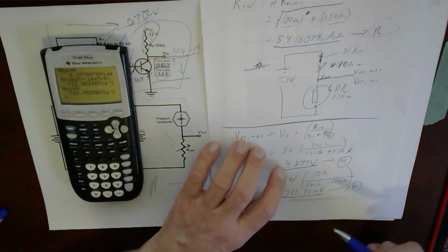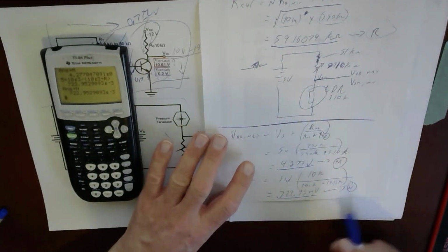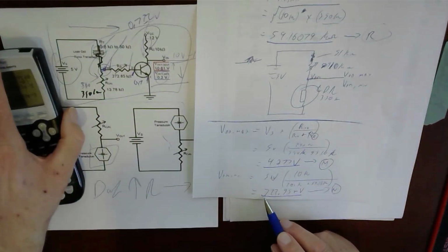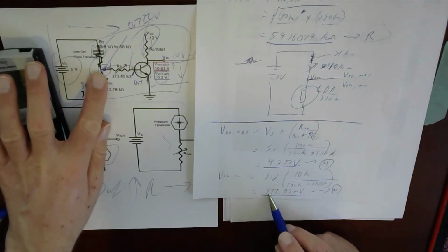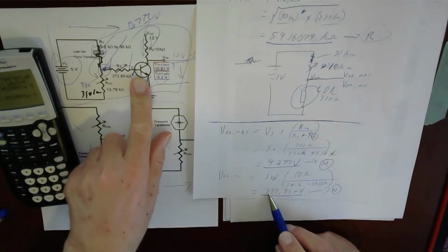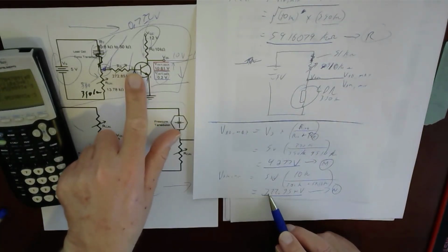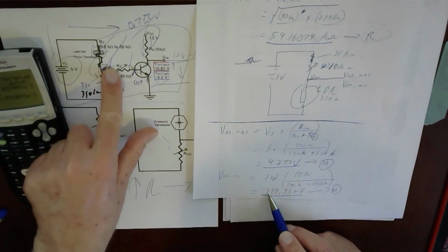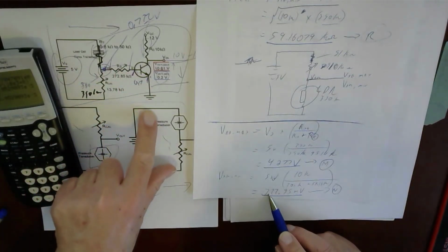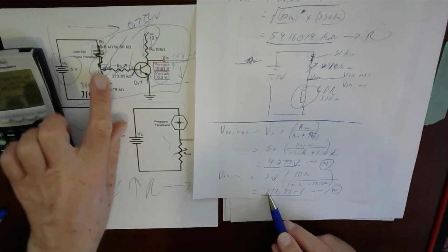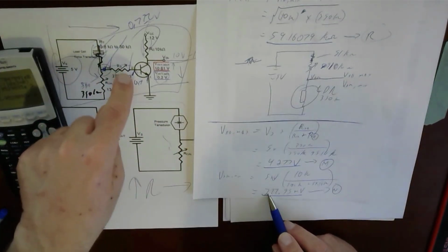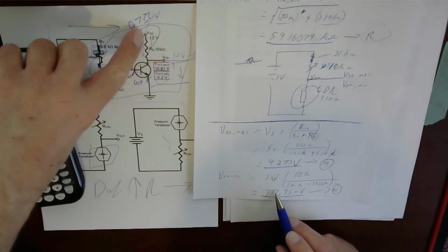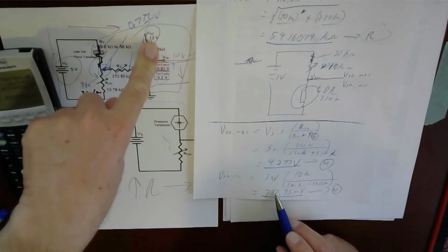That's maybe because I probably designed the numbers to do that. But what I'm saying is that when this is at its lowest, it's going to be 0.7 volts, which means that this is barely going to be closed, because the current's going to be so low through here. I only got 0.7 volts here. So I'm assuming that it's probably going to be close to whatever I put there.